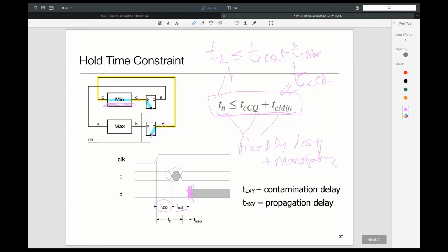And if I fail to do it, then I'll have a dud chip because there's absolutely nothing I can do once the design has been manufactured. So this one is a much more critical bug, right? If you have a hold time violation in your design, then you better fix it at design time because your chip isn't going to work.